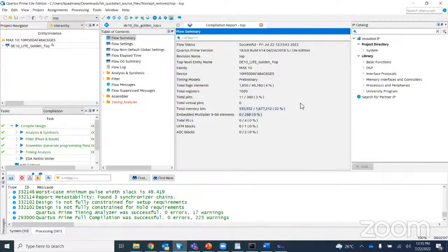Right, now you can see how many resources it has taken, compared to what was shown when you say estimate. Okay, but here if you see it has taken memory, but it has not taken any DSP resources. But when it was showing in the HLS estimation result, it has used 2 DSP resources, but it has not used any RAM.